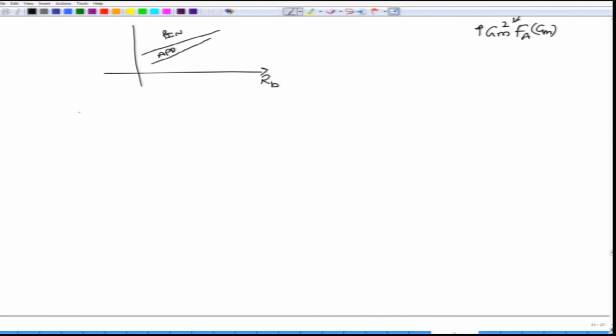Moving on to the next case, where you have an optical preamplifier. In the optical preamplifier case, what would be the major noise factor? Well, it is the signal beating with the spontaneous emission. This would be the case when you have transmitted bit 1. For bit 0, you have thermal noise and spontaneous noise, and shot noise is actually equal to 0 because you have transmitted bit 0 here.